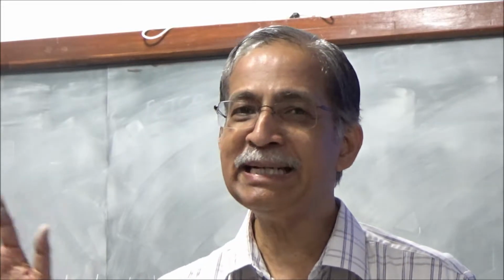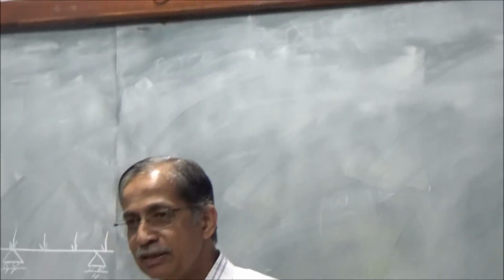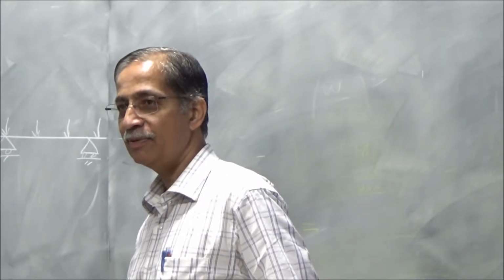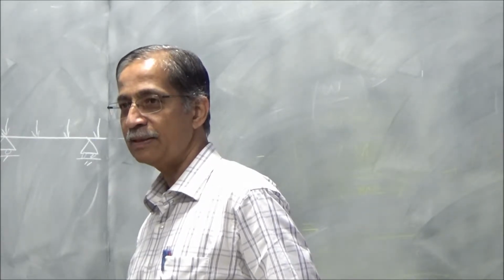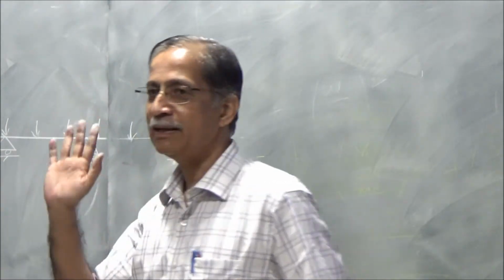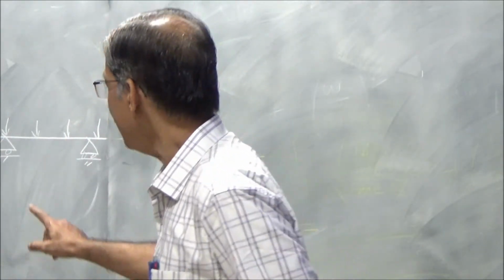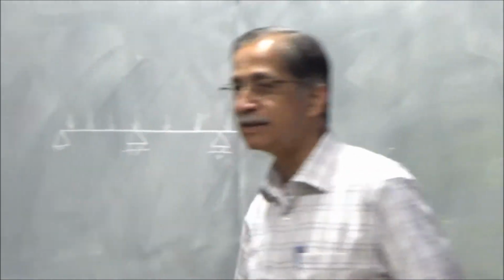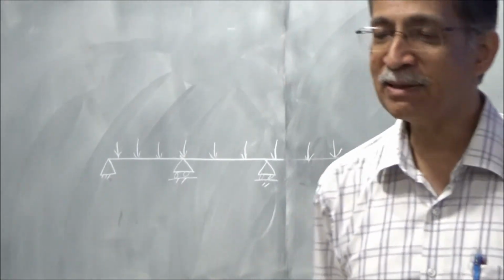No, loads we'll see later. First, the modeling. This is predominantly a load coming from the slab itself. Okay, there's no wall. Maybe you can assume some partition wall load. We model that as a UDL. Leave that. I'm talking about this first of all, modeling as a continuous system. Is it valid or not?